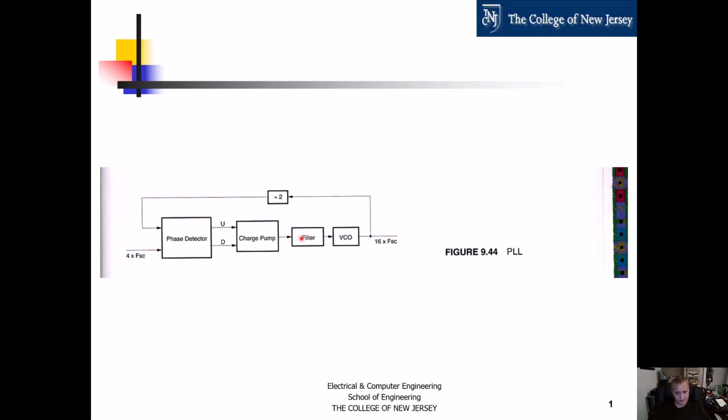Now, since this network is capacitive and we are driving it with current pulses from current sources, we're putting in a current, but here we are utilizing the voltage at the same node that the current is coming in or being drawn out. So since the voltage across the capacitor is the integral of the current, we're going to be getting voltage ramps up or ramps down at this node over here, which is the same as this one.